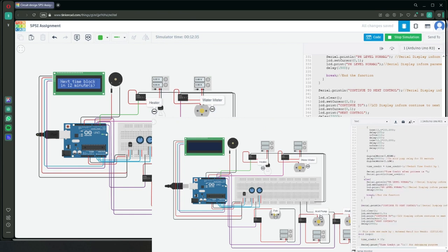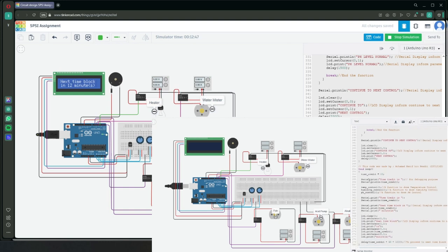For the idle time, which is the time that the system rests, the idle time should be equal to the balance of the remaining time credit left. So, once all the sensors have finished their function and loops, the time that is left in the time credit will be the time that the system rests.